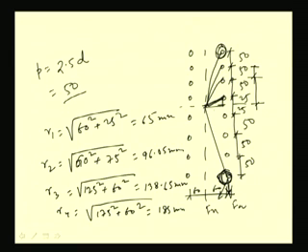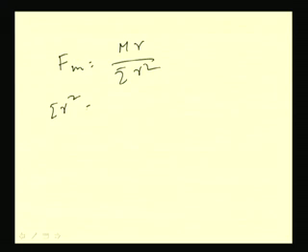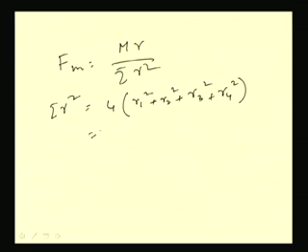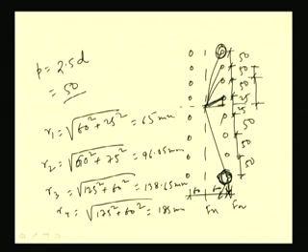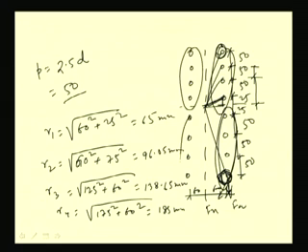Now, summation r square we have to make, because we know the force developed due to this moment is nothing but M r by summation r square. So, summation r square, let us find out. This will become 4 into r1 square plus r2 square plus r3 square plus r4 square. This is 4 because similar type of things, if we consider one row from here, then into 4 it will be.